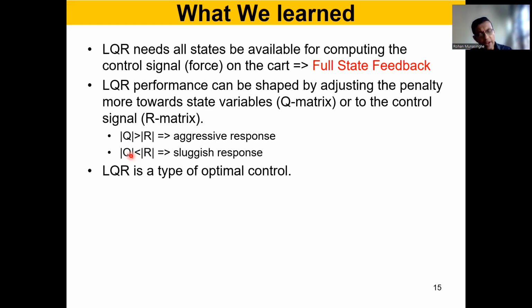But you have to go to quadratic if you want to have LQR. It has to be the quadratic regulator, so like x square terms, u square terms. And if you have many state variables, you have to take the square term of each and every one and add them together, and then give a relative importance to each state variable. So you are pretty much in the center of the controls. You can specify whatever you want in the cost function.